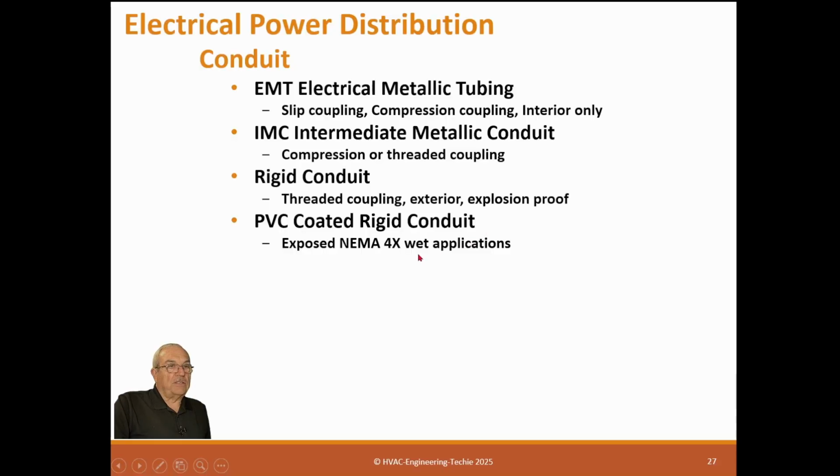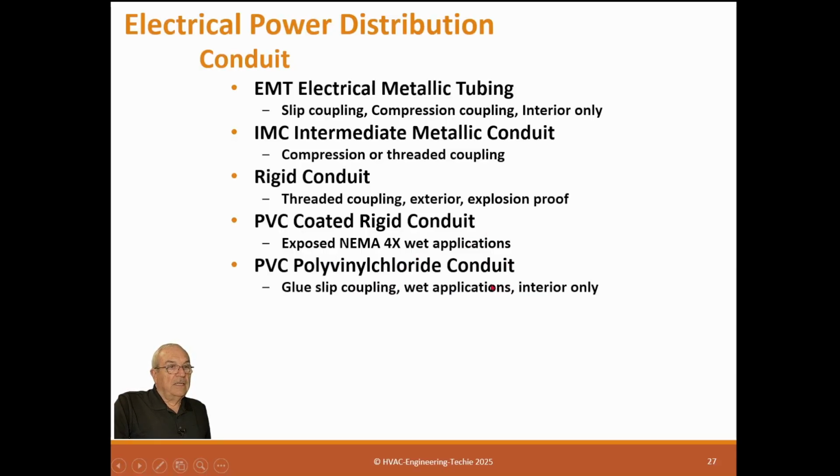Explosive, NEMA 4X, wet applications. PVC, polyvinyl chloride conduit, which is a glue slip fitting, wet applications, interior only. Sun will eat them up, so it's not for exterior use. They can be used underground.